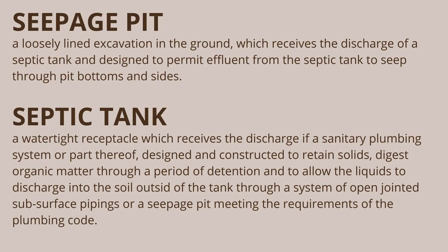Septic tank. A watertight receptacle which receives the discharge of a sanitary plumbing system or part thereof, designed and constructed to retain solids, digest organic matter through a period of detention and to allow the liquids to discharge into the soil outside of the tank through a system of open jointed subsurface pipings or a seepage pit meeting the requirements of the plumbing code.